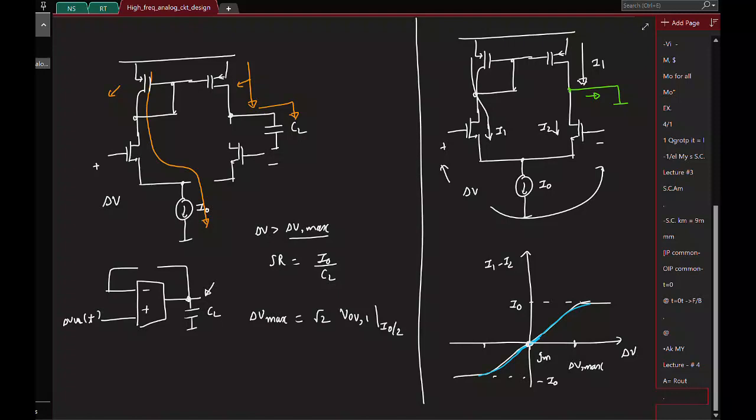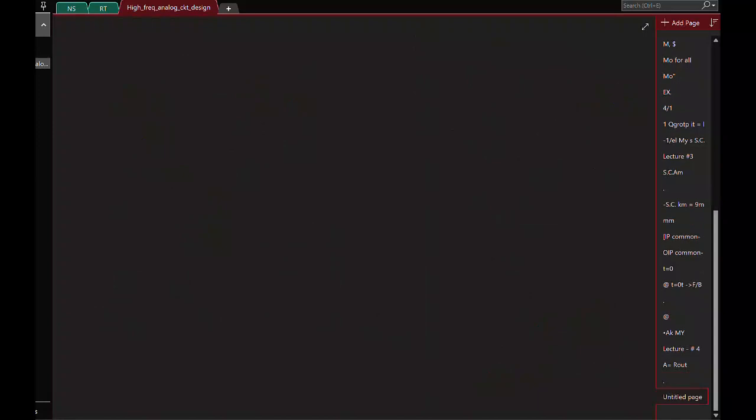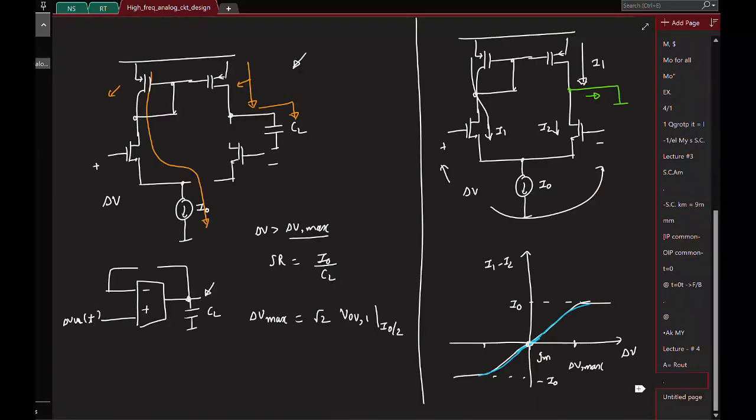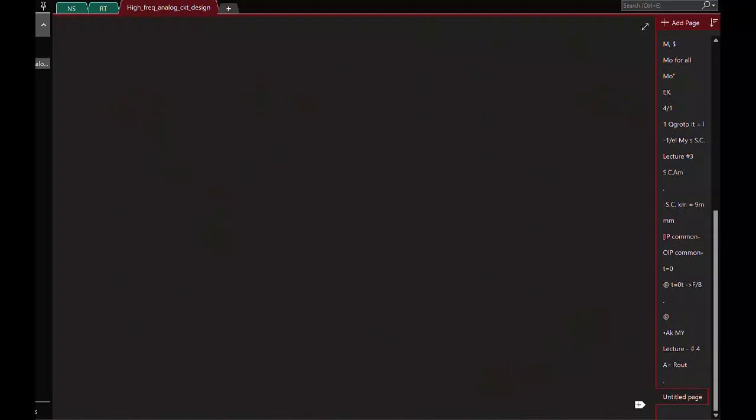Great. So now this 5 transistor OTA is actually pretty good. It will offer a decent gain, but in practice we need much higher gains. Okay, to give a range, probably this can get you gains at max 100 or something, but you might need gains of the order of millions or so. Okay, so this is not good enough.